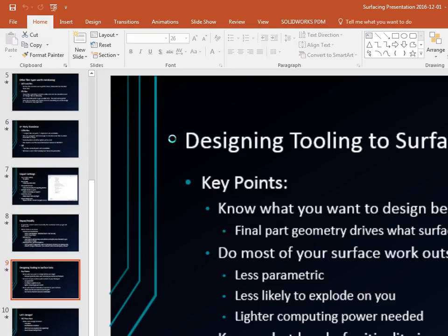Will it work on triangle shapes too? It'll work on any hole. I've had an issue with it trying to fill. If it's only breaking a single face, it's almost sure to work, in my experience, even if it's some bizarro hole. All you have to do is select one edge and do delete hole. Or were you saying untrim surface? The untrimmed surface, I think that would probably work too.